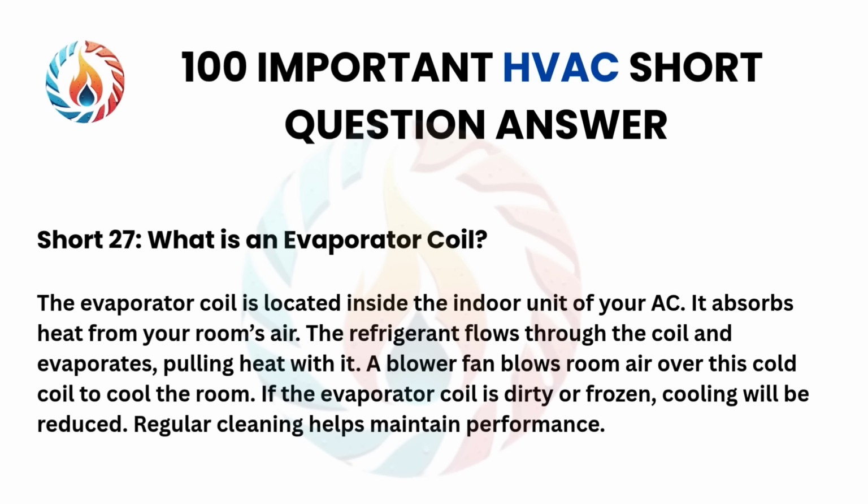A blower fan blows room air over this cold coil to cool the room. If the evaporator coil is dirty or frozen, cooling will be reduced. Regular cleaning helps maintain performance.